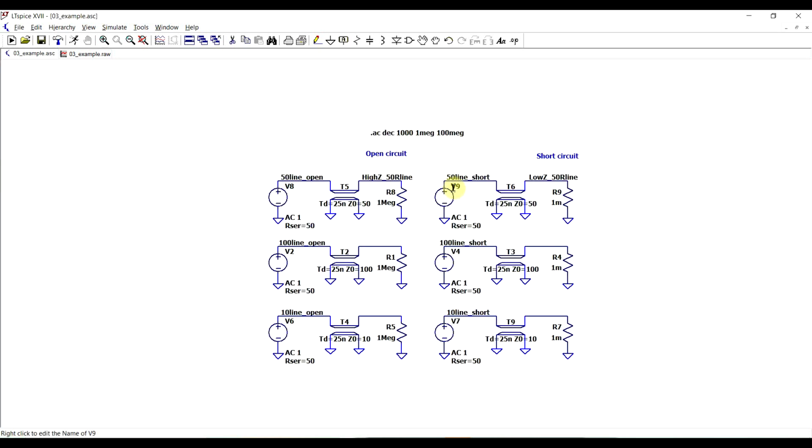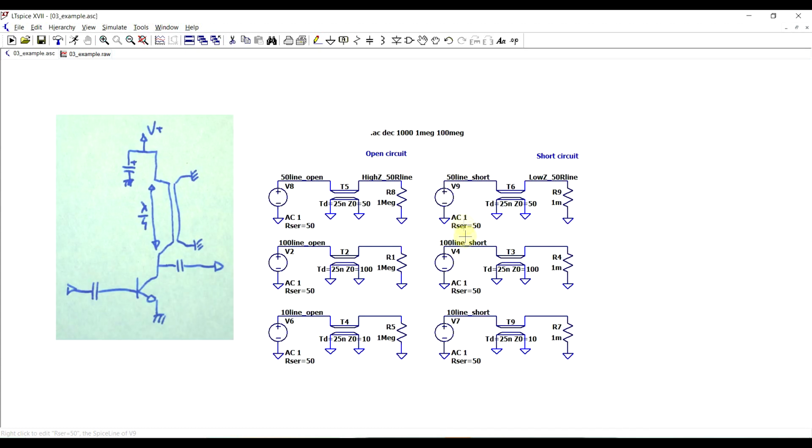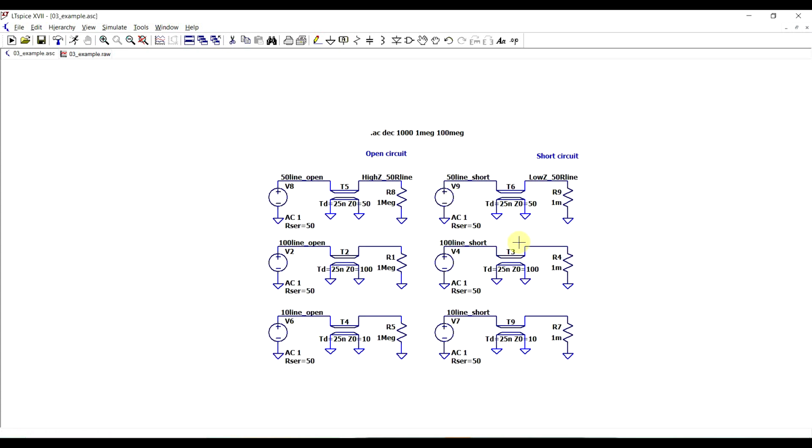So one use case for this sort of application is with supply lines. When your circuit is being supplied from a decoupling capacitor, the equivalent impedance is very small, but you don't really want to short circuit your signal source. So maybe this is the collector of a transistor. There you can use a quarter wavelength transmission line to isolate the decoupling capacitor from your circuit, so to form part of the biasing arrangement.